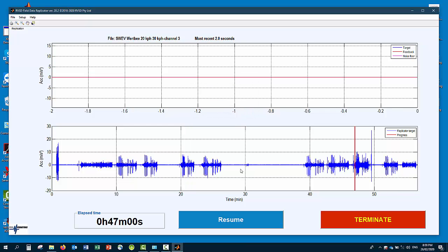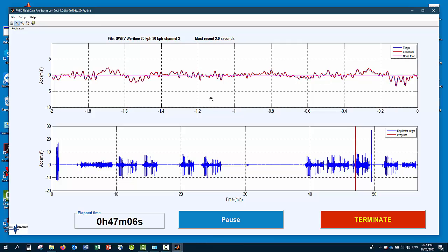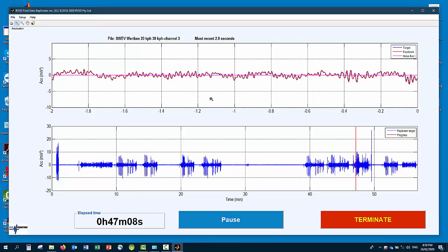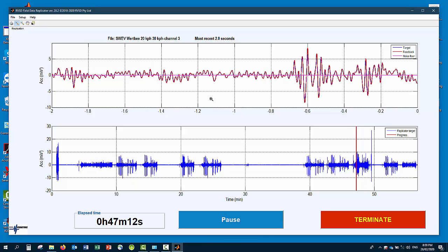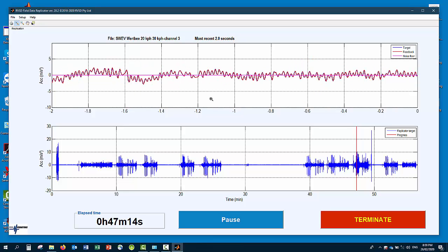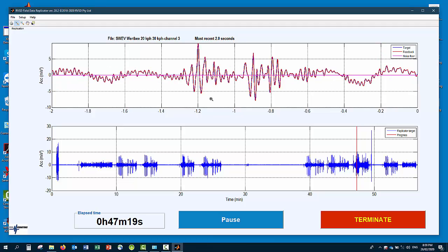And we'll see the cursor here, and I'll set my scale to 10, that's okay, resume. And I use the cursor to set my vertical scale to plus or minus 10 meters per second squared. And that's it. So it's a fairly simple system to use once you take the right steps, and hopefully it works as well as this when you try it on your own shaker.